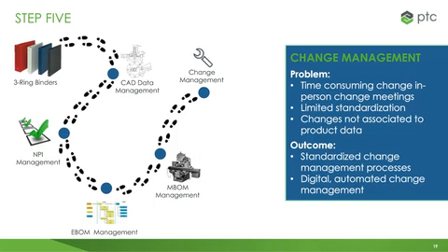Well, how did we address this? First thing we did is we implemented a CM2-like change management system for EBOMs and MBOMs inside PDM Link. The functionality already existed inside of PDM Link. We used it to standardize our change management processes. We configured and developed out-of-the-box workflows to automate the change management process.